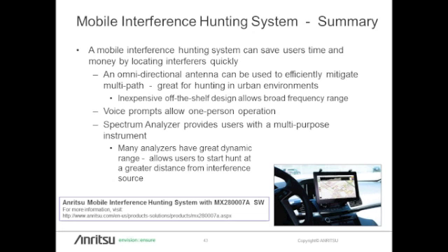So you want a good spectrum analyzer that's multi-purposed. It can do demodulations, it has a preamp, it can do channel bandwidth, min and max power, captures. With something good off-the-shelf, inexpensive, non-proprietary on the antenna, voice prompts, one-person operation. You want something that's multi-featured, for all types of interference and all types of environments, and that can give you a complete and comprehensive system.